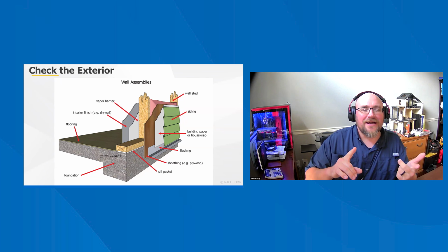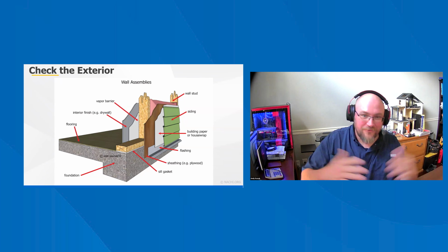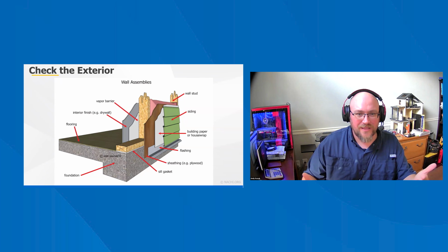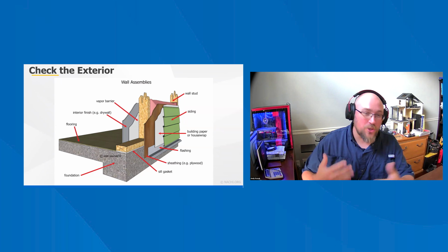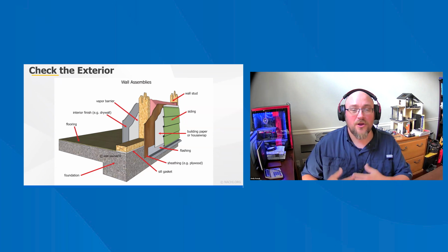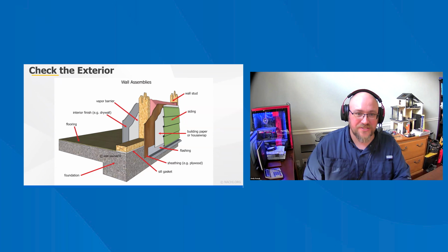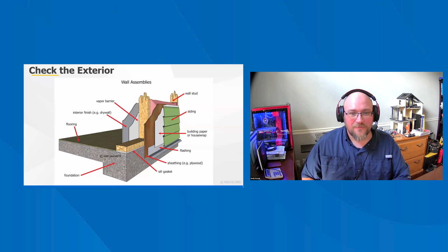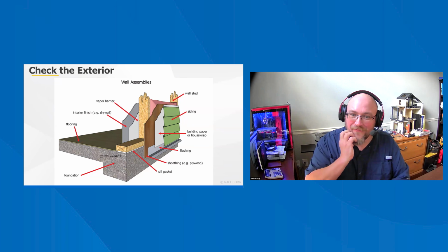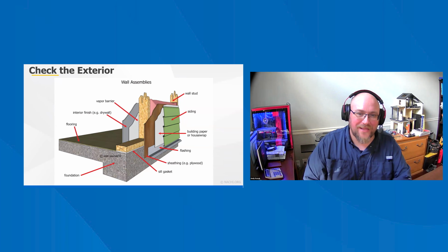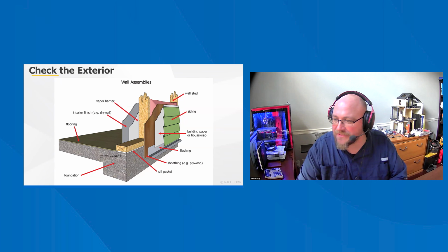Anyway, so now on zip tape, every joint is now a potential air infiltration or water infiltration point, which is why we're getting so much. I'm getting so many calls for water damage on new construction houses on these 500 thousand to 1 million, $2 million houses because of this. Everybody's using zip tape instead of house wrap now, and I just think it's so much less forgiving than house wrap. So just keep an eye on those things.